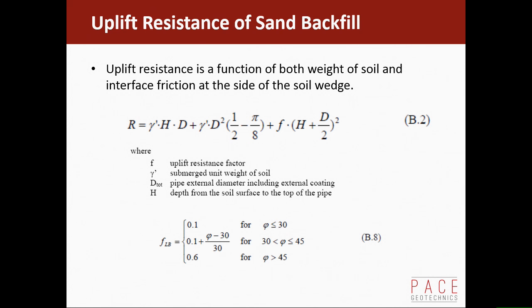I'm sure that's what's thrown me. The frictional value is a function of the friction angle, tan phi dashed. So you multiply that by tan phi dashed times K naught, and that section there is actually your F value. Okay, so that's just a function of those two components.